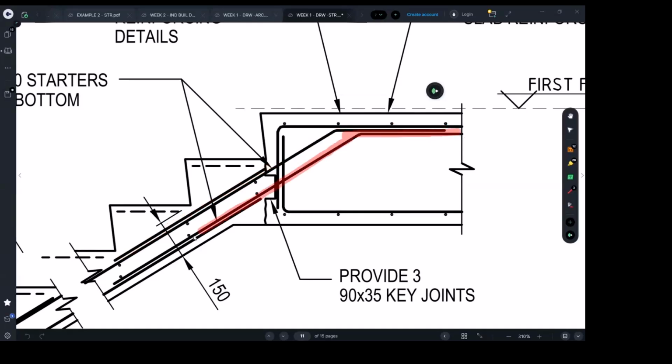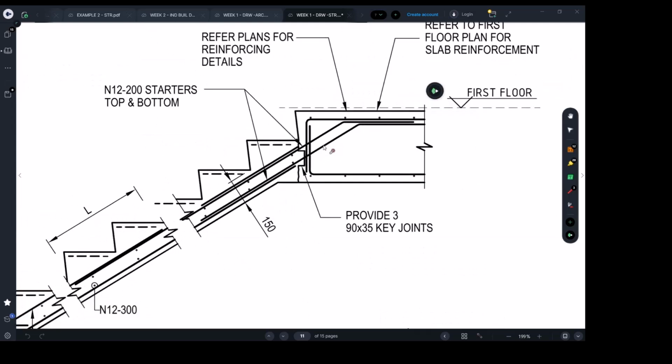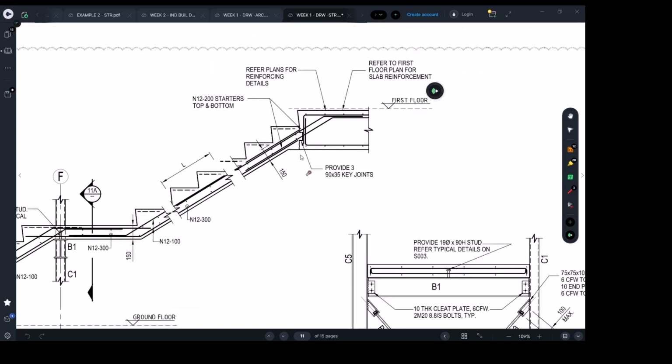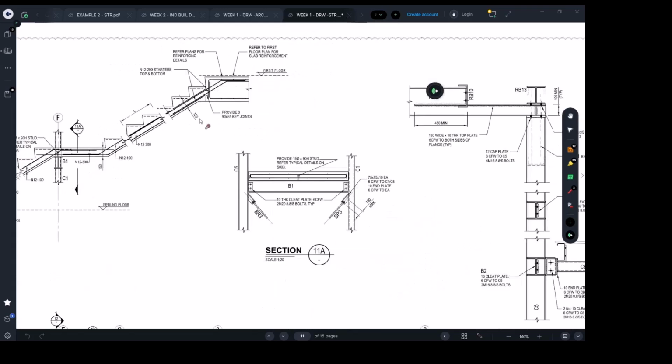It's going to be a problem if you miss them. Before you actually pour this slab, you have to make sure they are in place. They are simple things on site. They're going to be maybe only 15 bars. And people miss these things. If you miss them, it's going to cost you maybe a day, 2 days, and you need to call another company, another contractor, to come. You have to drill and epoxy. If you forgot this, you're going to have to drill and use chemicals to put in a stronger bar. So there are small details. If misread, not done, this will cost you a day or two, and you know each day means money. So that's it. So from this sheet, if people select it and specify which detail is used, so be it.